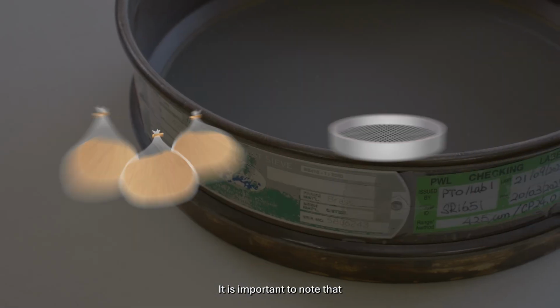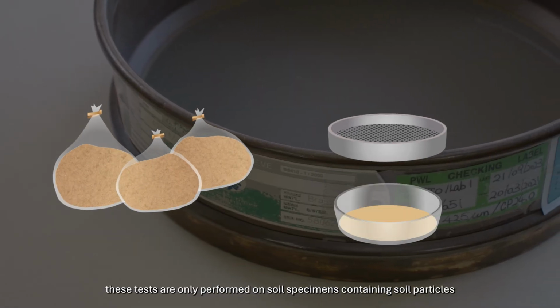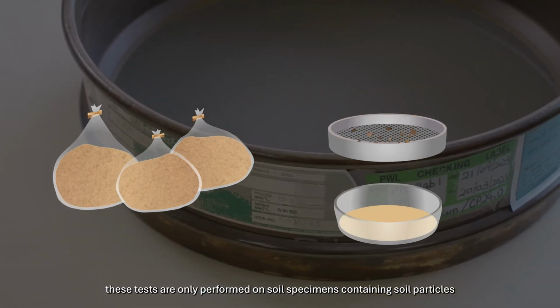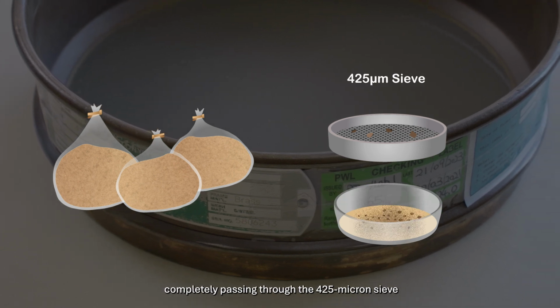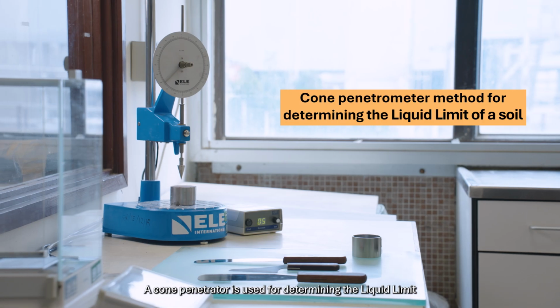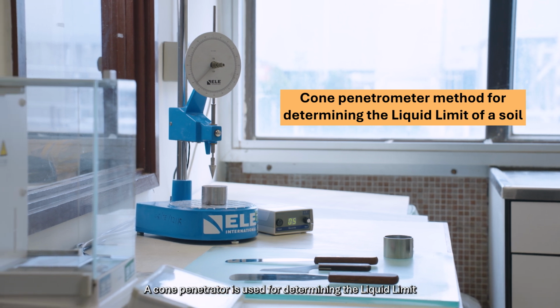It is important to note that these tests are only performed on soil specimens containing soil particles completely passing through the 425 micron sieve. A cone penetrometer is used for determining the liquid limit.